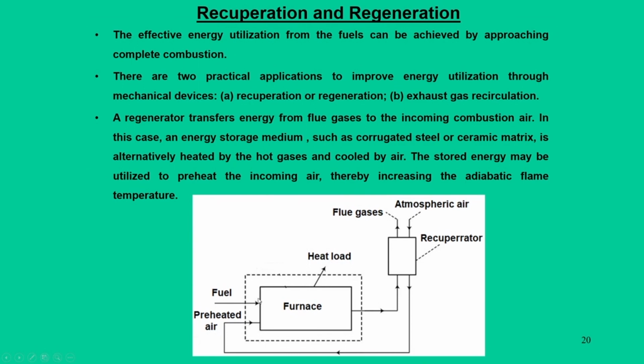Whichever way, if you preheat the air, what it essentially does is improve or increase the adiabatic flame temperature. When such a regenerator or recuperator is used, we can use a lean mixture, because in lean combustion we have burned the fuel sufficiently, but the exhaust product still has sufficient heat. In such situations, the regeneration or recuperation concept can be used to tap the heat.